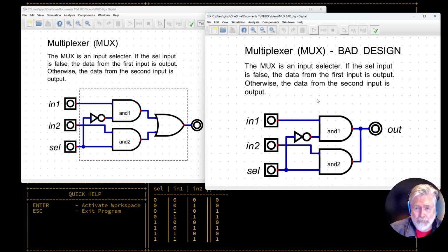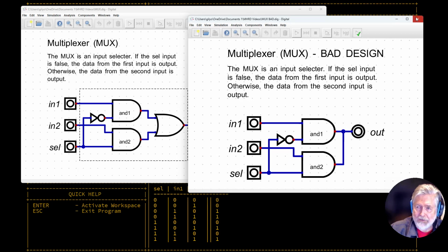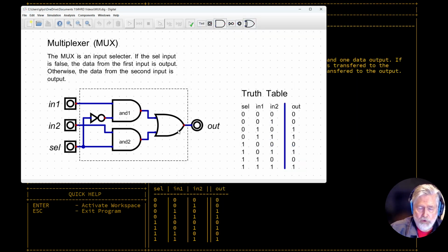So it's not that much different, but because of the logical way the program's working, this was flagged as an error. That's okay. This will definitely work, and it's probably a better design. A little bit slower because you have electronic circuits going on in the OR gate. That slows it down a little bit, whereas just a direct wire like I had it would be a little bit faster than the integrated circuit would be. But this multiplexer works just right.